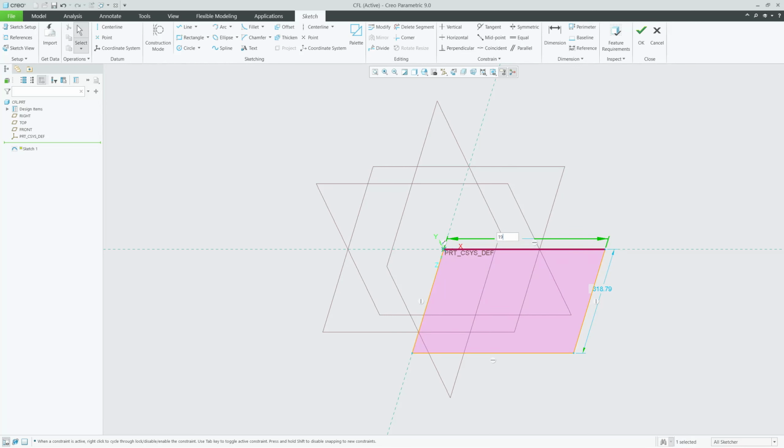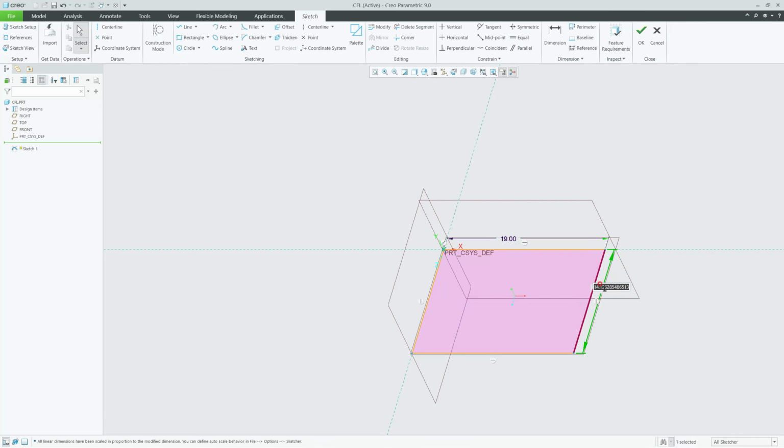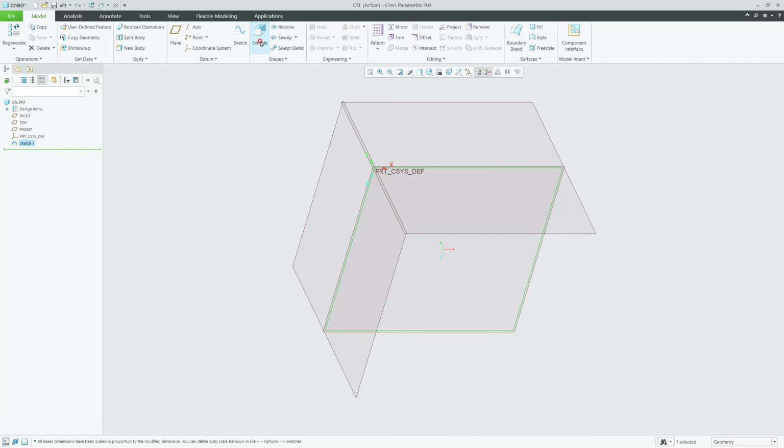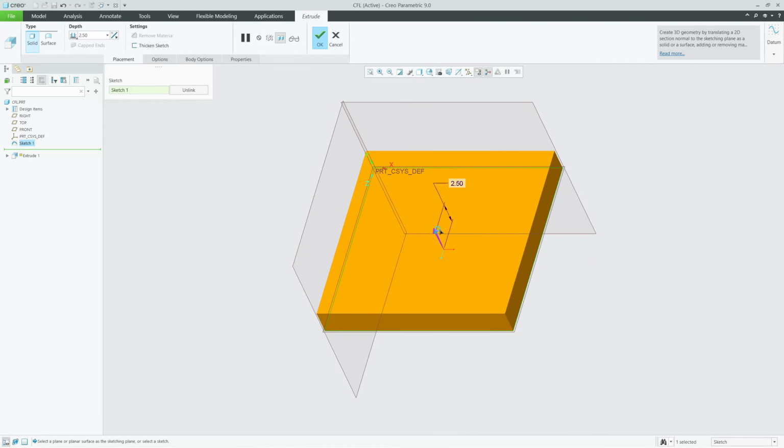This will be 19 mm by 19 mm, and okay, and then if you try to extrude it, that will be equal to 0.01. Now it's out of range. So either we shift our units to micron and set the tolerance accordingly, or we can just directly set the tolerance and then do our job in mm's. But tolerance is the main thing that we need to change.